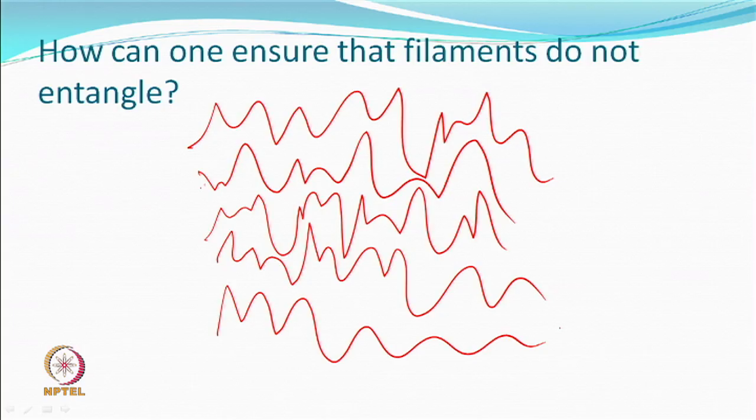We have seen air jet, we have seen interlacement, some entanglement takes place. Because if it gets entangled, then it will be a different product. Yeah? By changing frequency and amplitude of bending. Yeah, but this amplitude and frequency change is not a very controlled phenomenon, it is an expected phenomenon. The control with you is the pressure and the temperature. They are the control that you have.